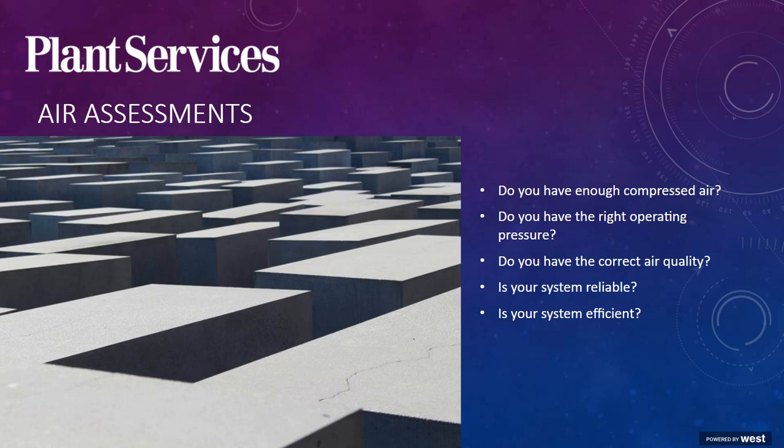Using an assessment or air audit gives plant owners and operators a clear picture of how their system operates, as well as how much energy it consumes, if the system is reliable, if it has the right air quality, and the most telling point is an air audit is going to tell you how efficiently the compressed air system is actually running based on a key performance indicator, or KPI, called specific power.